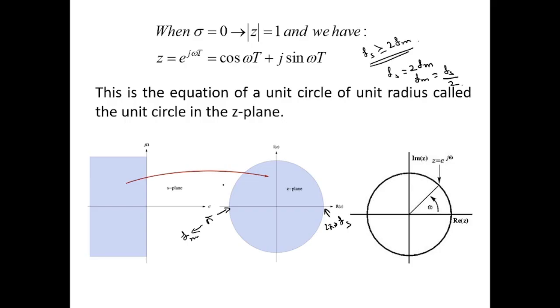Okay. So because of this, if you want to look into the frequency component 0 to 2 pi, and this is the amplitude, we'll be having 0 to pi, which is fm. And again we said that when we are sampling the signal, we are basically mirroring the frequency component.